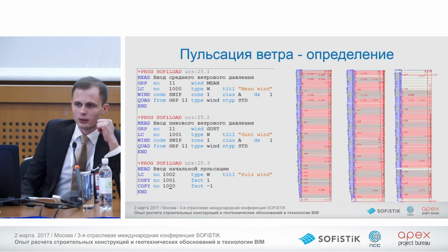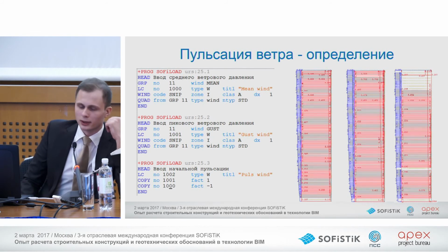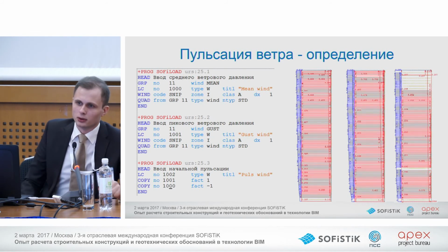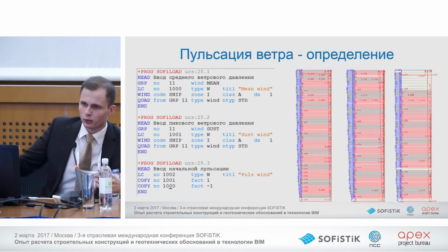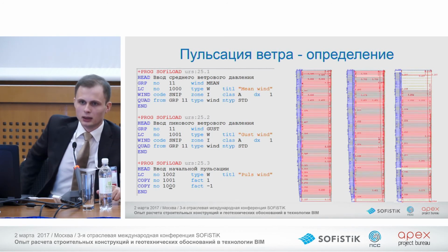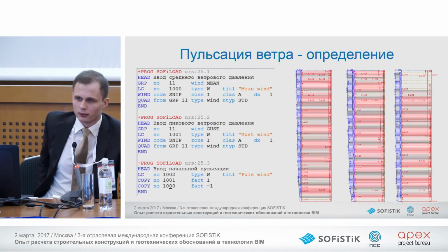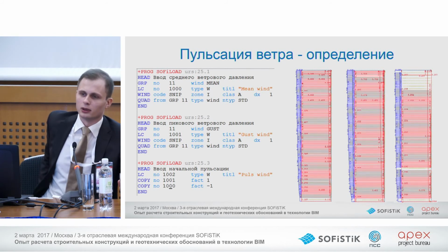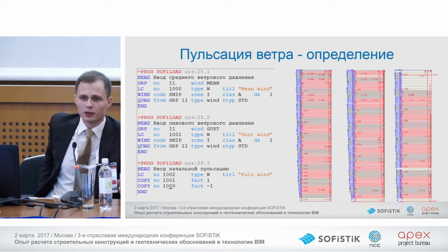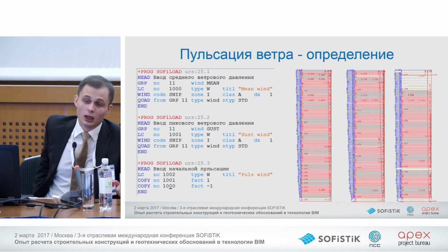In SOFiSTIK software, load can automatically apply such loads and distribute them. We have 2 modes. One is average wind pressure, and second is peak wind pressure.